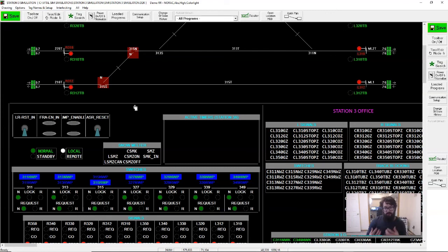So that's another element where if you don't simulate that action, your simulation model is going to think that element has just gone dead. So the simulation has to be able to provide not just a visualization for switches and search lamps, but it also has to emulate that machine behavior of a motor actually turning and setting some of your feedback to a new value when you change your outputs.